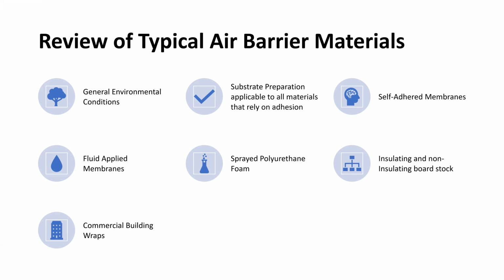Where one can be installed in plus 70 and the other can be installed in minus 50. It's like they've all got this kind of band that they can be installed with. And the same kind of happens when it comes to substrate prep. Substrate prep for one material is generally going to be the same for other materials that rely on adhesion. And then you'll have some materials that are mechanically fastened. And again, the principles of how we attach them mechanically tend to be the same. So I call those the general things.